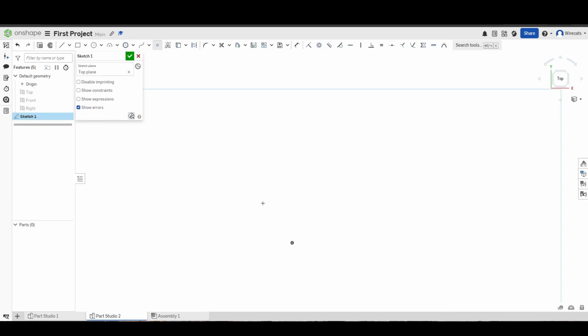The point tool is pretty simple. The shortcut is Shift plus S by default. You click Shift S and then you can pretty much make points. You'll notice that these points aren't constrained, but for example, if I make a dimension between these two, and let's say I want to go this way, 4mm.